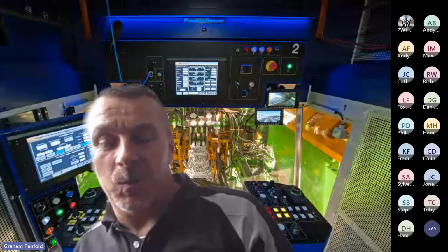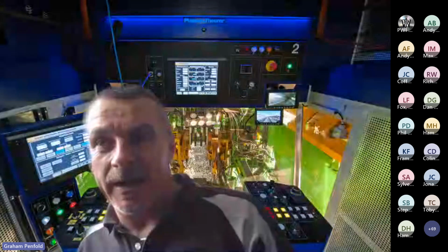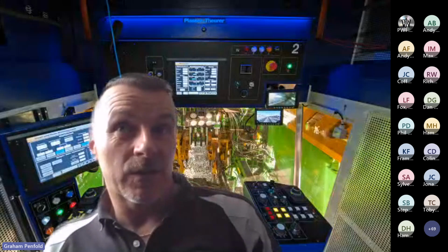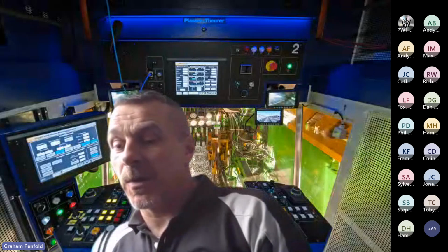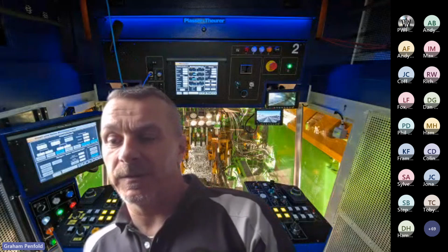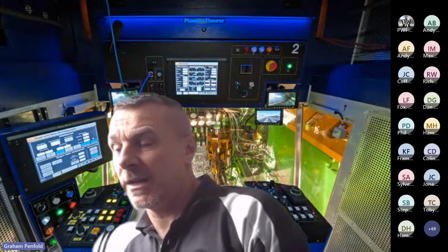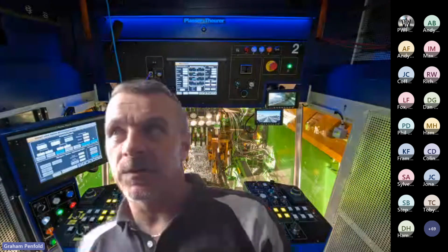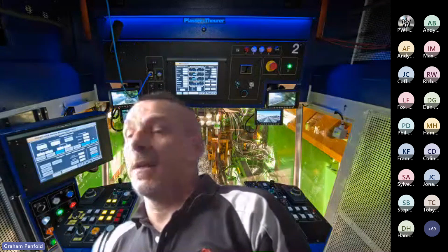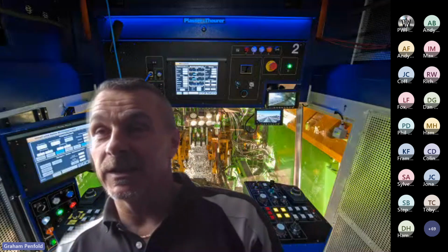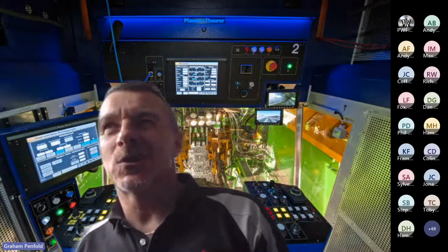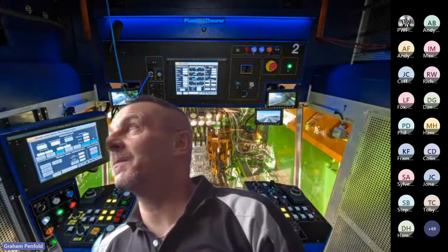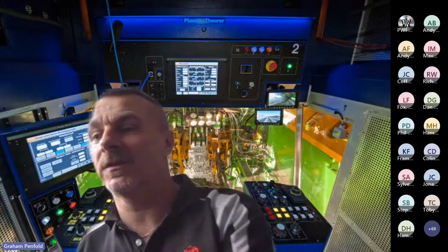If you go back to one of the last points I said, we apply DTS settlement compensation under wires, knowing that DTS will settle the track. So initially, our design lifts with our DTS settlement compensation are technically non-compliant, but then DTS comes in, vibrates the track and settles the track right back down to the compliant. Exactly the same would happen to ATG, but I'm pretty sure they wouldn't use it. But it's something that I can speak to Errol about. To me, if they did use it, they would get similar results to us.